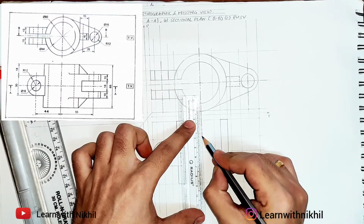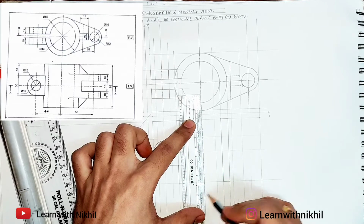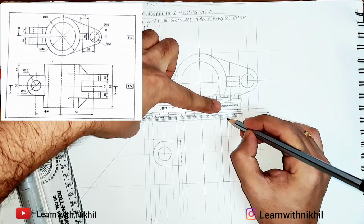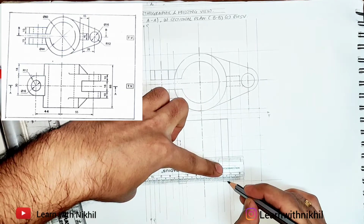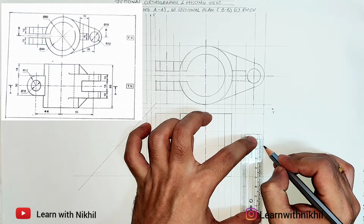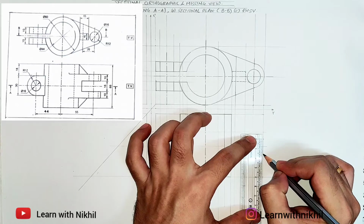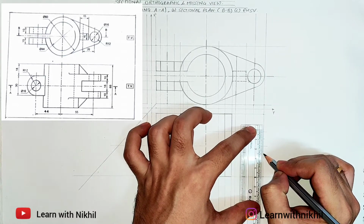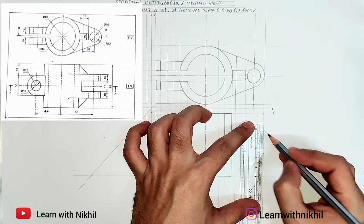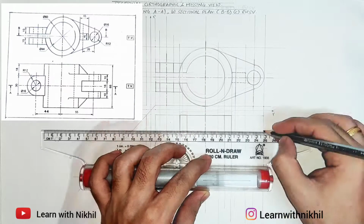Drawing the circle center line, extending this downward. Joining this dark also. This is the outer circle, which looks like a rectangle shape. Drawing this part from the center, 8 mm above, 8 mm below. So the height is 16. Then from those points, 10 mm above, and from here 10 mm below will be the thickness of this part.